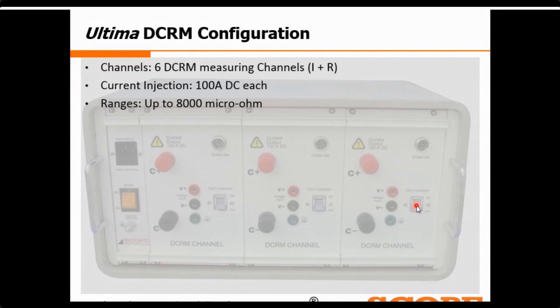The measuring speed is 50 microseconds at 20 kilocycles, so you get the complete picture at 50 microsecond intervals in the DCRM measurement. That is how accurate and good the measuring speed is. Within a 50 microsecond interval, we give you the indication of the circuit breaker contacts.